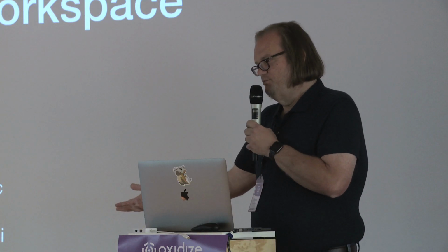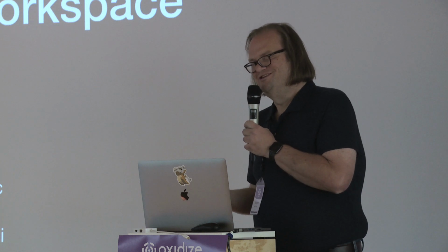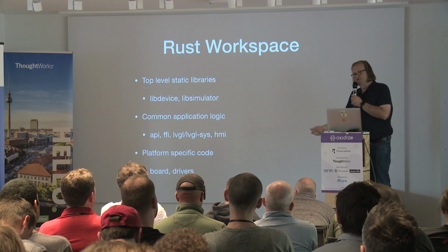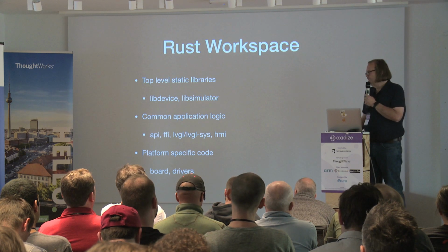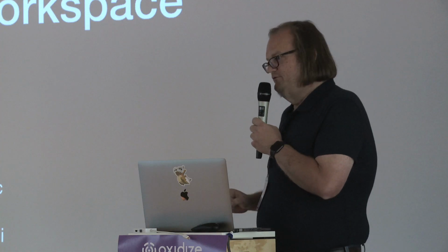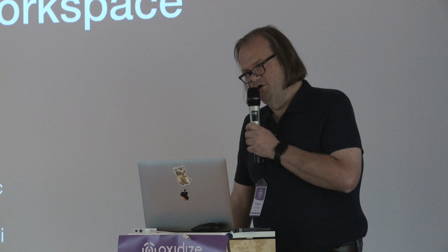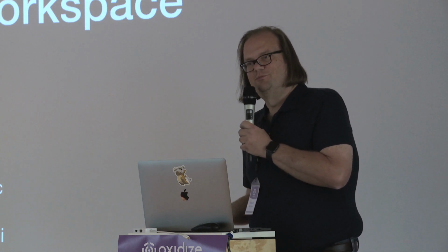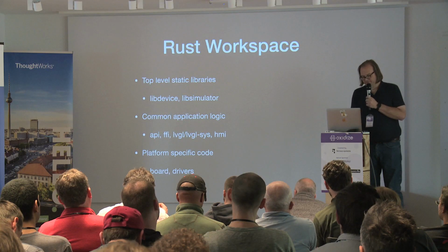The board crate brings together all of the embedded crates, the Cortex crates, the embedded HALs, and puts them into one place where they're easy to manage. And then the drivers crate is able to use the embedded HAL APIs to define interfaces to the buttons and the LEDs.